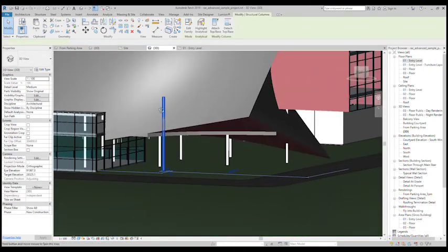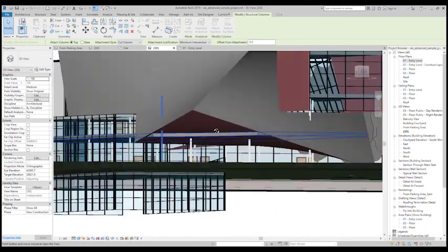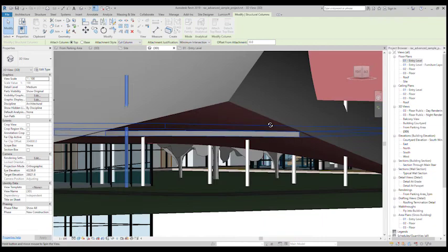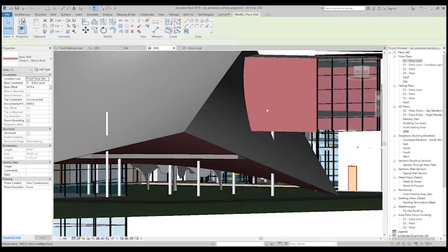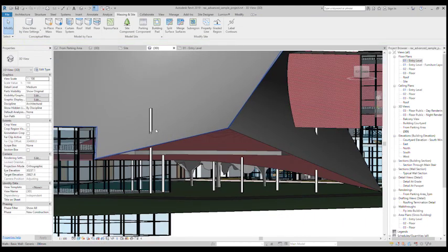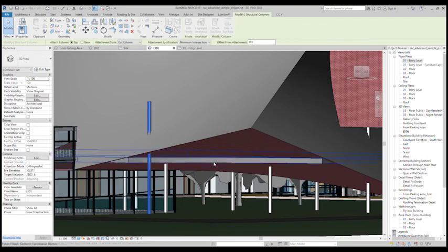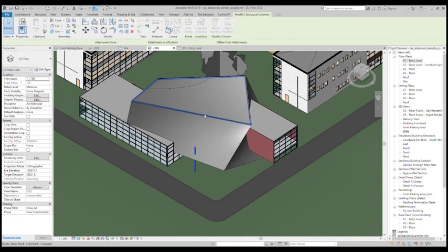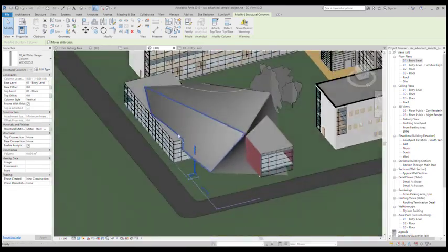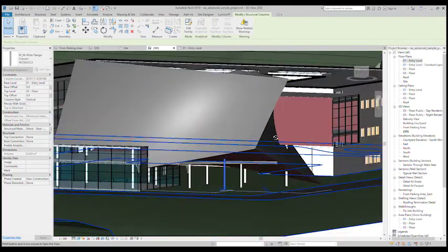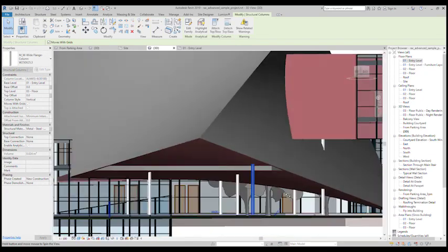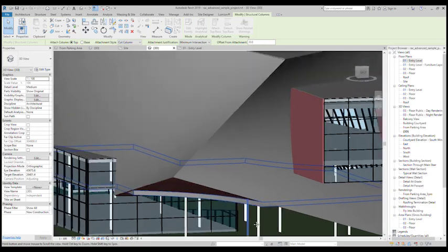Let's try it with this column, for example. I'm going to attach it, and you see I can't select that red wall, obviously, because there isn't anything anymore. Let me just place another wall there. Nope. Okay, it is still there. Never mind. You can't attach columns to walls. Obviously, you can only attach them to either floors or roofs. So this column I'm going to bring up. Oh, sorry, it's not really intersecting with that roof. So I have to bring it in or attach it to that floor, which is sitting there. Okay. So attach to the roof.